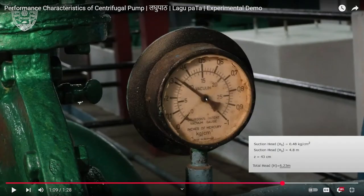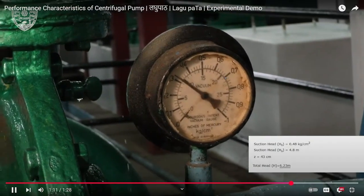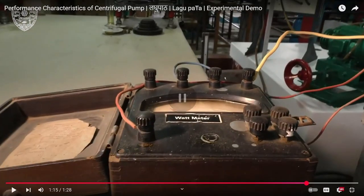So here also you can see the suction pressure. This is the suction pressure, somewhere around 0.32, okay, while the discharge pressure was at 0.7 or 0.8 kg per centimeter square. Head pressure reading corresponding to the discharge. Calculate the total head. So based on these pressure values, we can compute the total head. So that thing is done.